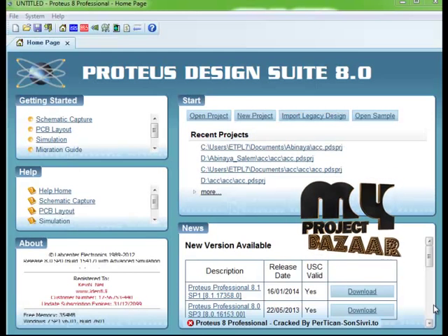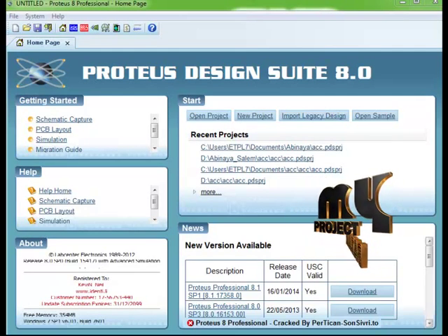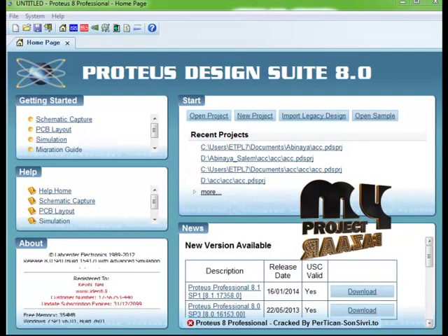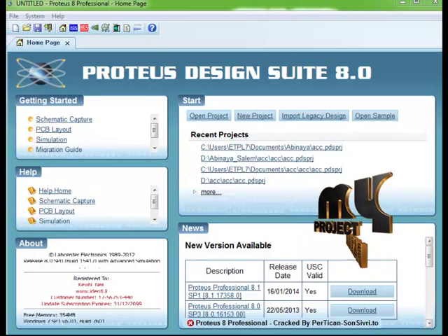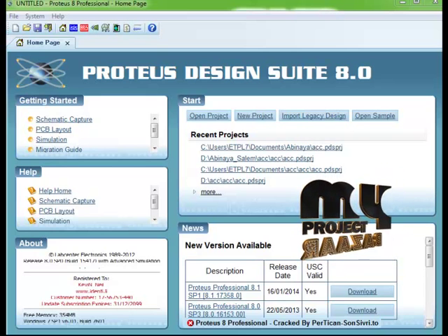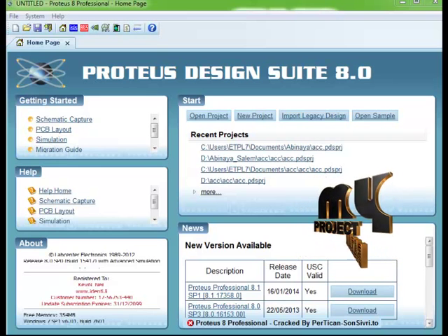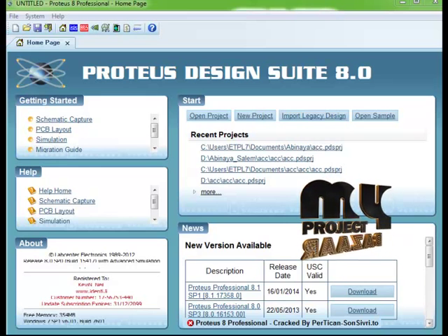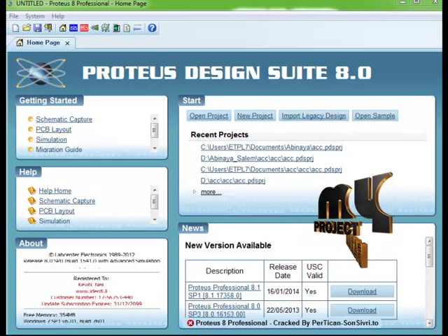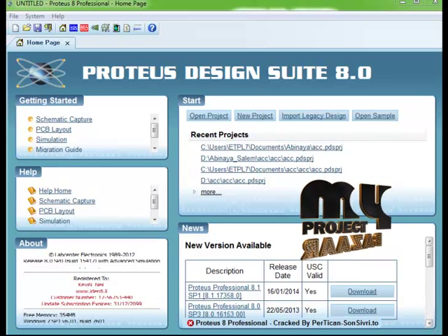We have developed this process in a new tool, that is Proteus software. Why we go for the software is that in Proteus we can design the microcontroller in a specific manner, and then we can display the results also. First, in the Proteus software, we design the input supply, that is we give the VCC supply and the connections are given to the ground.